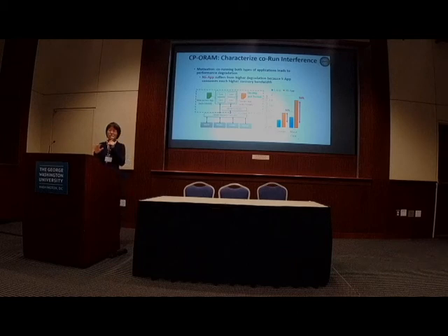Instead of using parallel memory channels, the buffer-on-board uses serial memory channels. The parallel memory channels use a lot of pins, but a serial memory channel is narrower than a parallel channel, and the serial links have a high frequency. So you achieve equivalent memory bandwidth, but you occupy very few pins.